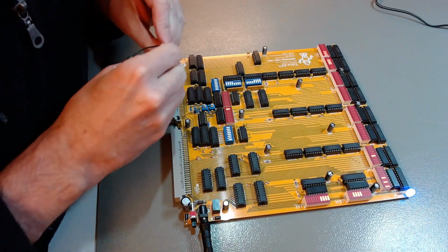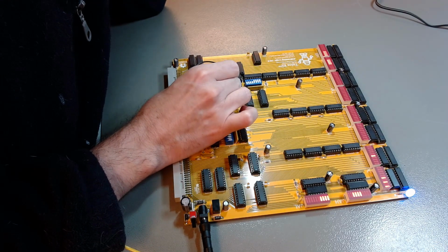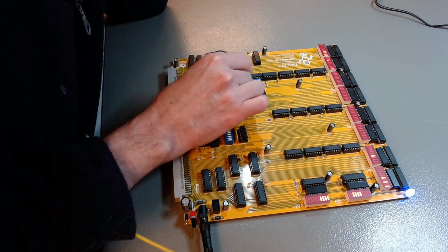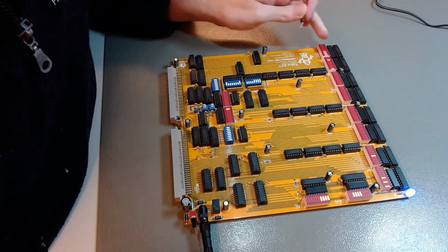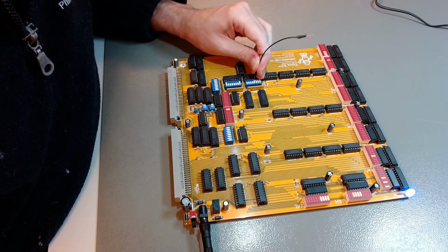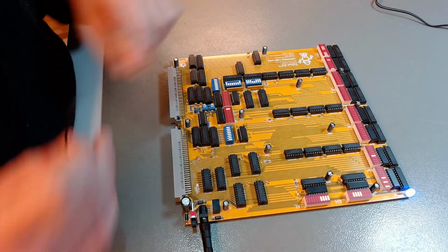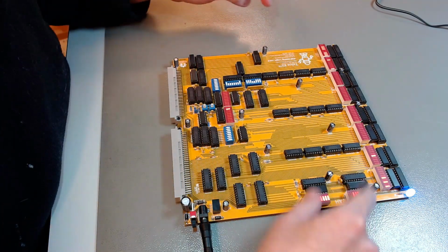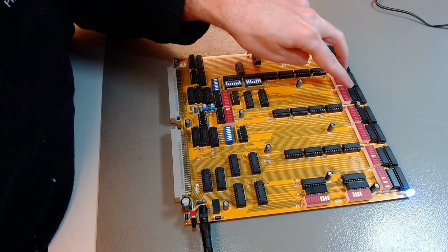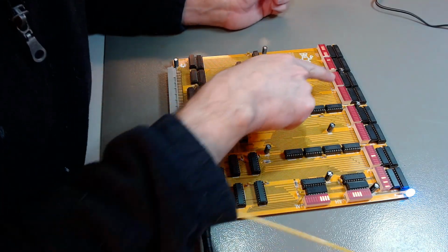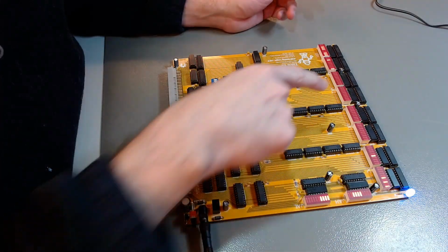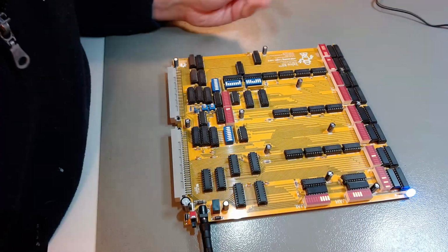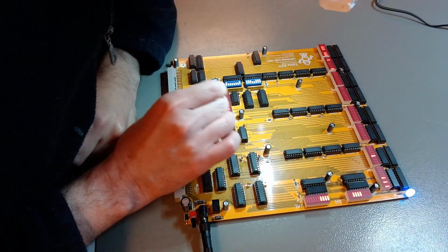Now let's change the dip switches here and put some other values. I'll keep the 2 bits on the extremes on, and for this one I have to do something else: I put 2 bits in the middle off, and the other bits on the extremes are on, just so we have a different value than this. So let's load this on both address registers. There will be no instruction that will load both address registers at the same time, because they're supposed to be different indices, so I cannot imagine a situation where you want to preload them with the same value. But the hardware allows for it, so to test the hardware, we do it.